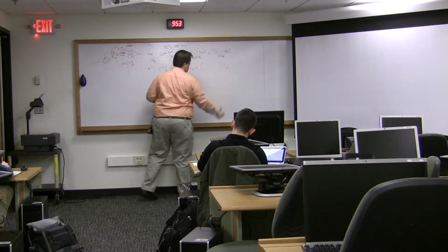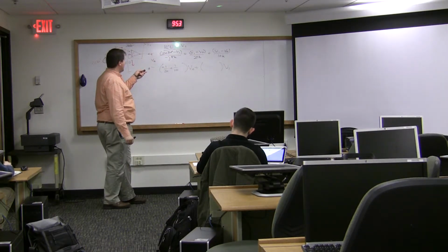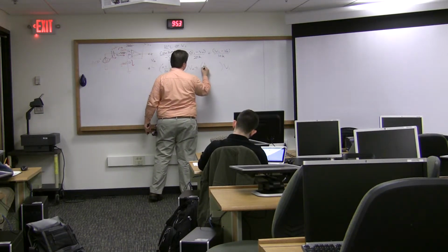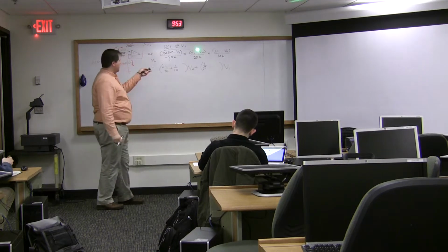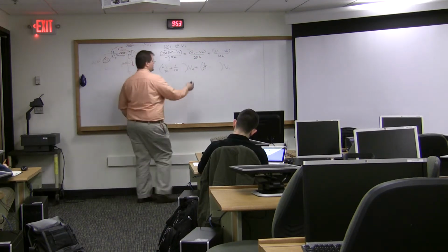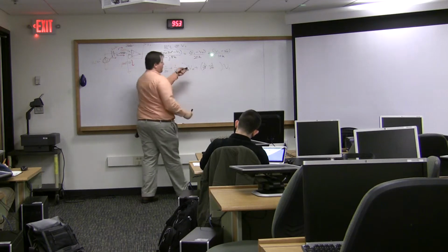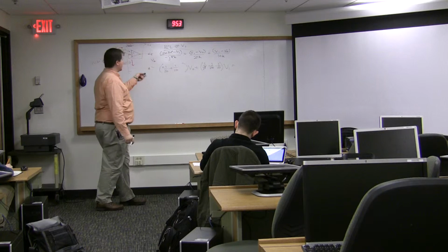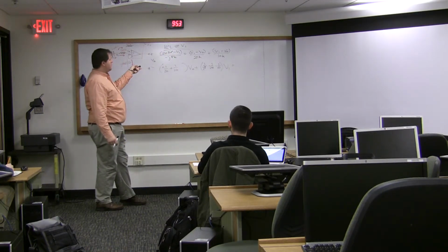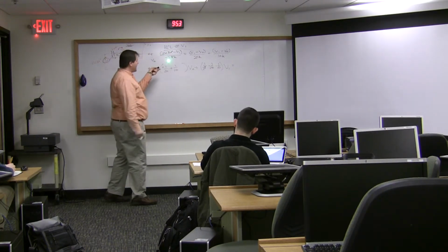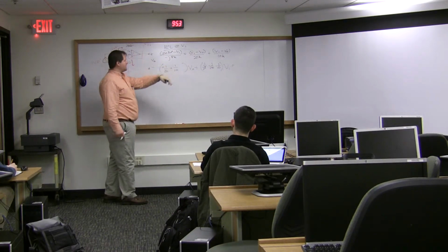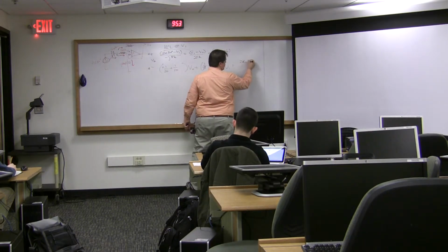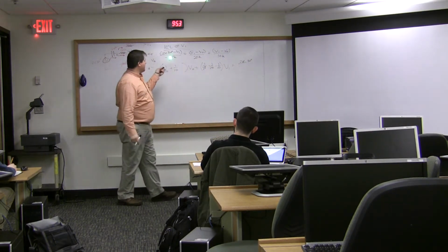Plus all the coefficients of V1, and I have negative 1 over negative j8, so that's a positive 1 over j8. From the right-hand side, the 1 over 20 gets subtracted, and the 1 over 10 gets subtracted. And that all equals my constant term, which is the 2 phase of 30 divided by negative j8, but that has to be added to the right side, which counteracts the minus sign. So I have 2 phase of 30 degrees divided by j8.